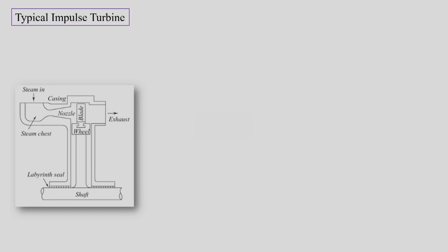So a typical impulse turbine is this way, where we will have a nozzle. First the steam will be coming from the boiler inside a nozzle, and the nozzle initially will have total enthalpy H naught at the entry of it, where we will have P naught as the pressure and T naught as the temperature. These correspond to the boiler outlet, and then the flow expands inside the nozzle and attains very high velocity at the outlet of the nozzle. So at the expense of the enthalpy drop in the nozzle, we get an increase in kinetic energy of the flow.